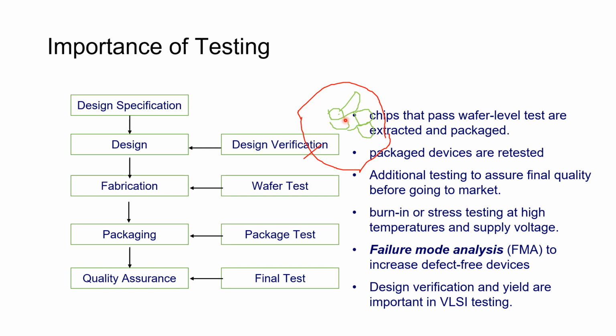Right. So these are all dies, and there are many dies of the same size within the wafer. You have to understand what is a wafer and what is a die. So we test at the wafer level. Once you test the wafer, you find out which are good dies and bad dies. You cut out the actual dies with machinery, and good dies will get packaged.